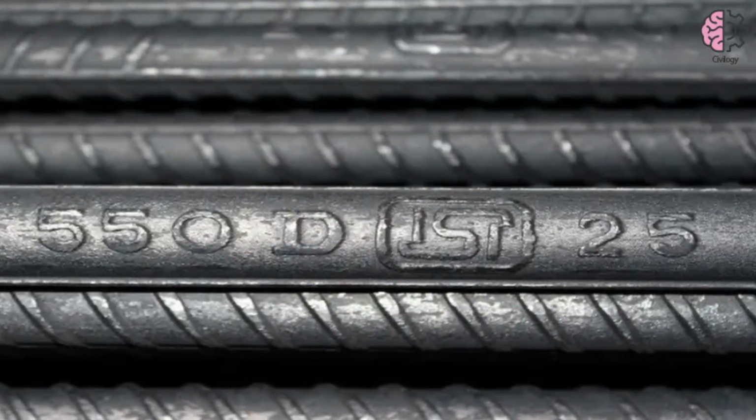Sometimes engineers might want to use it, so it depends on the risk you're taking in putting it in your slab or floor or anything. That's an important part. The steel also has a nomenclature, a name marked on it, like Fe415 or Fe500 or Fe550. This tells you what type of steel is being delivered, and what's on the steel. So this is very important.